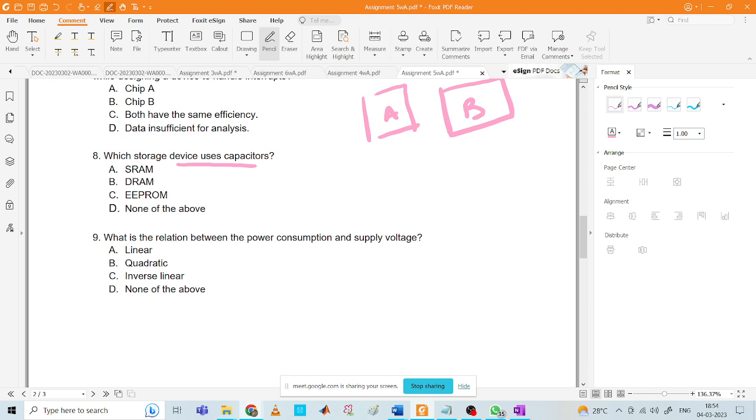DRAM. Yes. So in DRAM you also need charging, discharging, refresh circuitry. Because DRAM uses a capacitor, it needs to be refreshed again and again, and that is the reason it requires refreshing circuitry, which is extra circuitry. So that's why you specifically need one DDR controller.